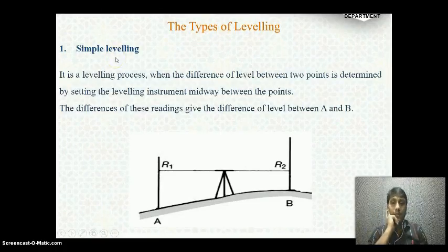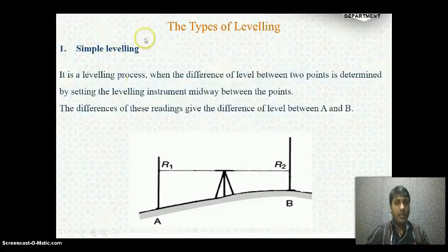So now coming to the types of leveling. I will just give you a brief explanation. You can read these things here. Simple leveling: when you have only two stations, where you know one station's RL and you need to find another station's RL, then this leveling is known as simple leveling.